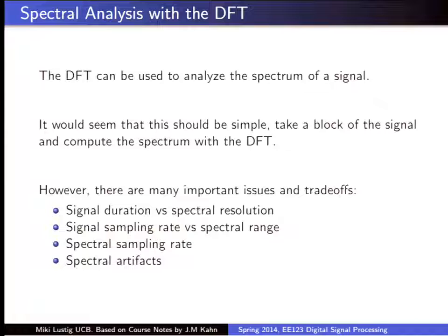So we're going to use the DFT to analyze the spectrum of a signal. And yes, it appears to be simple. You take a signal, compute the DFT, and look at the spectrum. But there are trade-offs. There are all these subtleties in the DFT, in digital signal processing, that you have to take care of, because you're approximating things, dealing with discrete signals, discrete time and finite signals, so you have to be careful and understand what is actually going on.